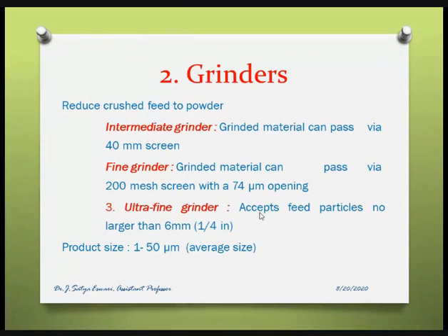Next are ultrafine grinders. They accept feed particles no larger than 6 mm or 1/4 inch, and the product size is 1 to 50 micrometer average size.